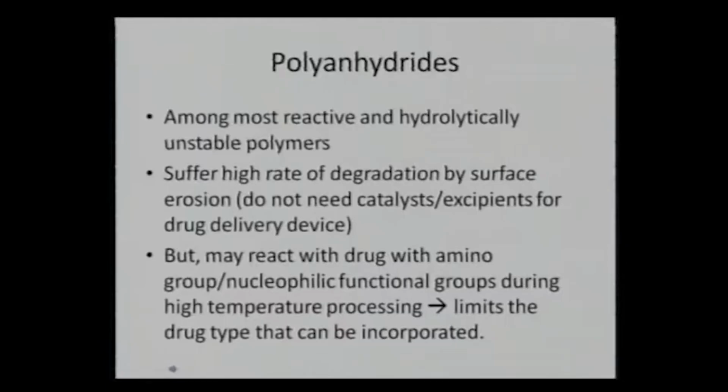If they are aliphatic, they can degrade within a couple of days. If they are aromatic, they take a couple of years to degrade, and that provides better control in terms of engineering this polyanhydride as a biodegradable polymer. And again, the advantage with these polyanhydrides is they are among the most reactive and hydrolytically unstable polymers. So though we say polyanhydrides can range from a couple of days to a couple of years of degradation, they are very reactive and hydrolytically unstable polymers. So they have both advantages as well as disadvantages.